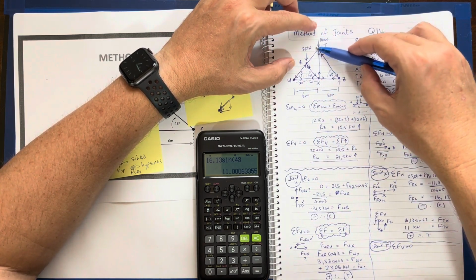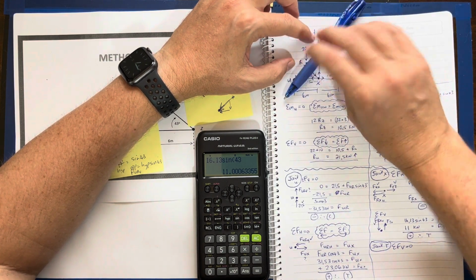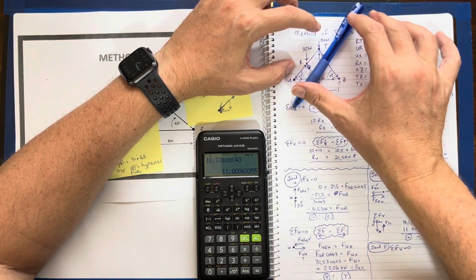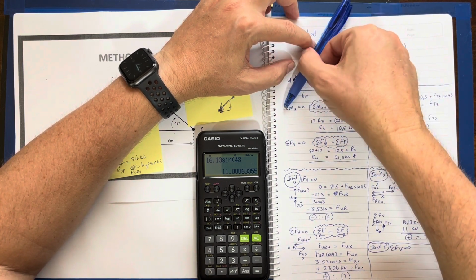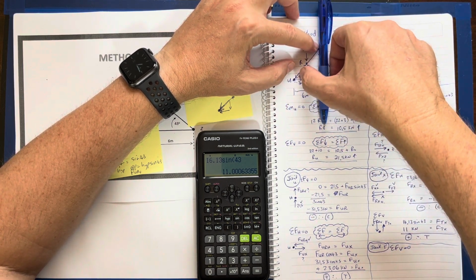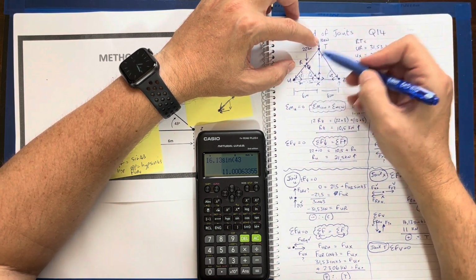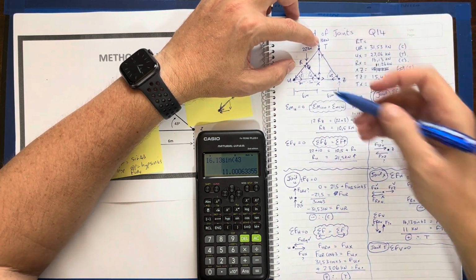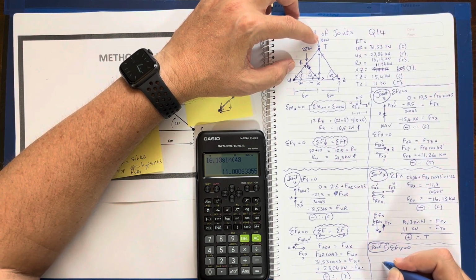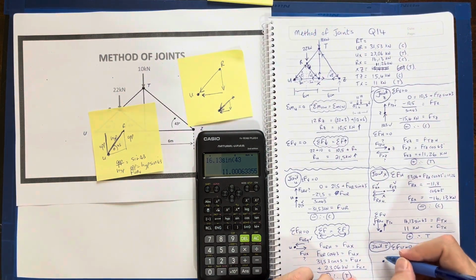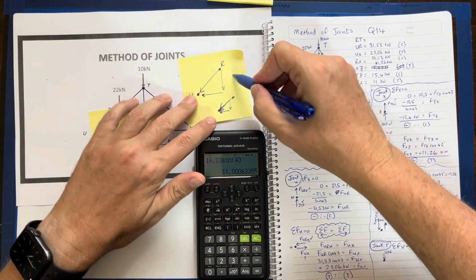I also have this external force of 10. And I can find RT's equivalent vertical because it's a hypotenuse, so it's going to be the hypotenuse sine 43, because the whole triangle is 43. So let me draw this joint. Straight away, my first external force is going down, 10 kilonewtons.